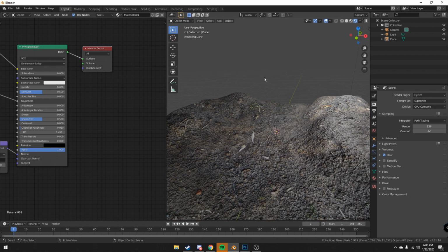That's basically what UV unwrapping is. It's taking your mesh, laying it flat, and then having the texture pasted on it. Now you can resize these, reshape them, and move them around to map the texture to it. Now, if you have a really big model, UV unwrapping gets really difficult.